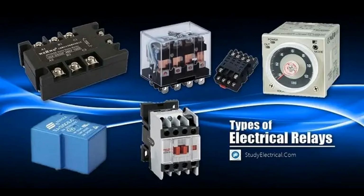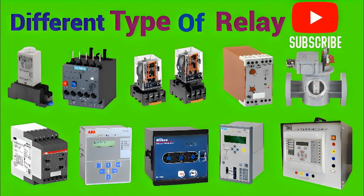In automotive applications, relays are extensively used for various functions due to their ability to handle high currents and voltages reliably. Here are some common automotive applications of relays. Headlights. Relays are often employed to control the headlights in vehicles. The headlight switch typically sends a low current signal to activate the relay, which then connects the high current circuit that powers the headlights. This setup helps prevent excessive current flow through the headlight switch, prolonging its lifespan.